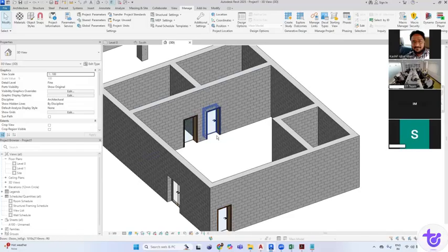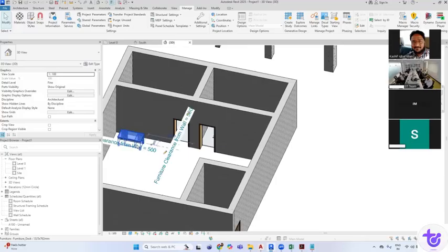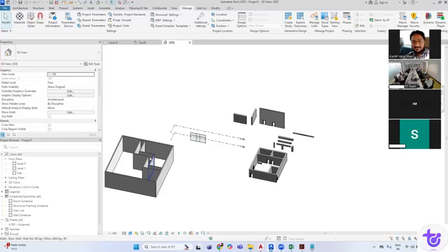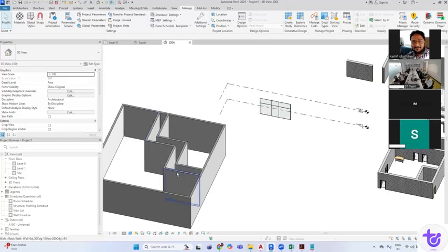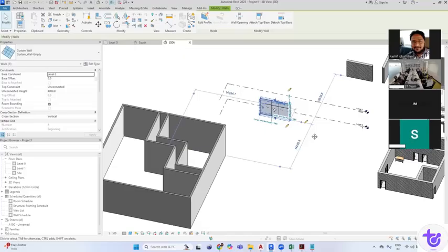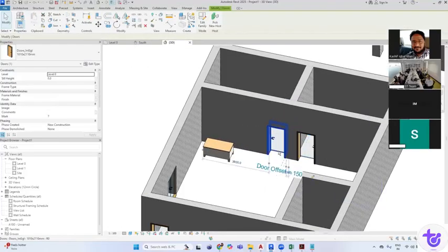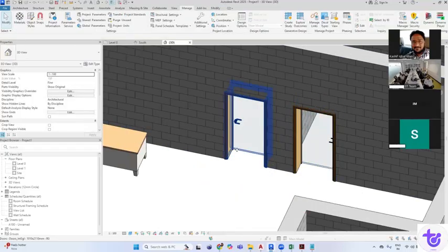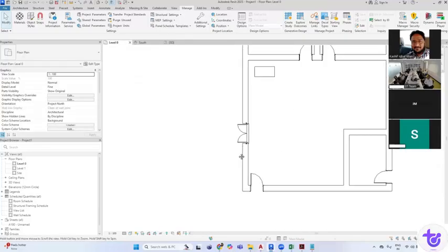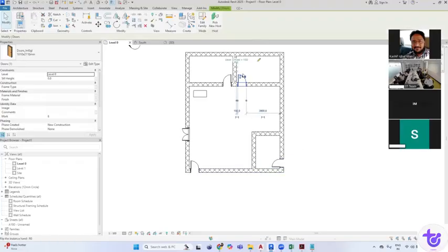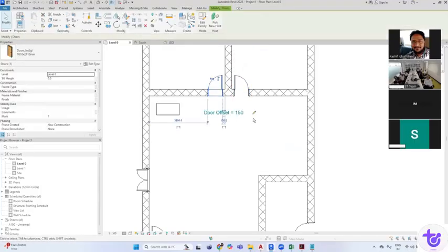Not only specifically to the door material, you can change the furniture material as well. Anything. More specifically, I found it more useful for constraining the dimensions, particularly for door offset from the wall. This is always a pain. Sometimes it displaces. So we can just add a dimension and set it to the global parameter. And then you can delete the dimension also, because if it looks ugly there in the floor plan, two dimensions floating, you can delete. But still, the parameter has been set there.